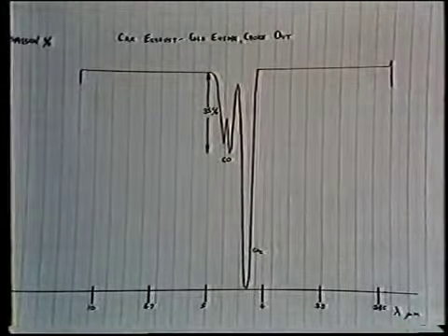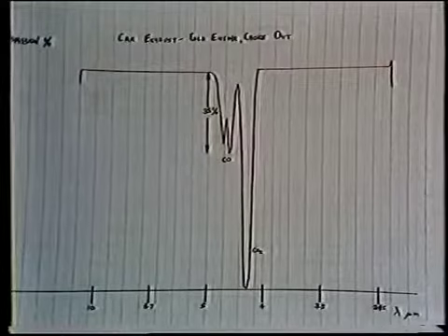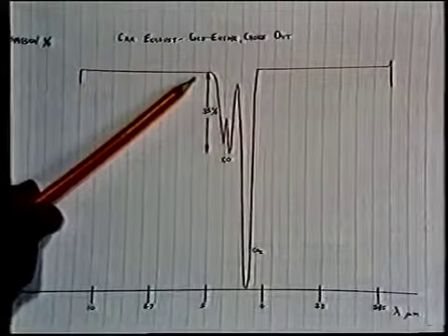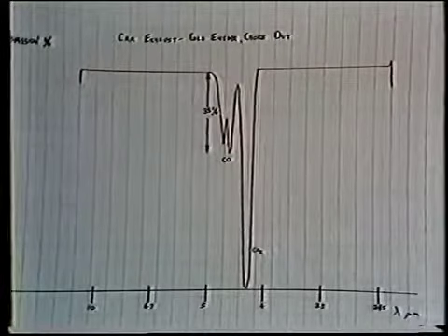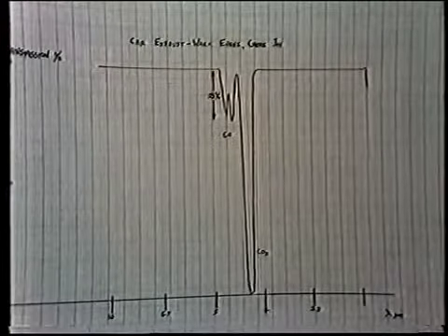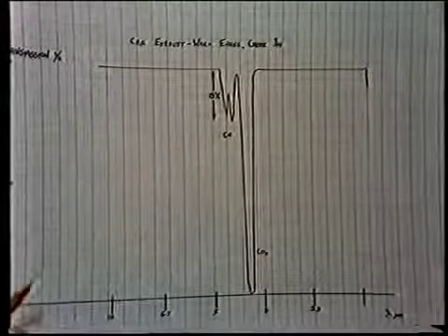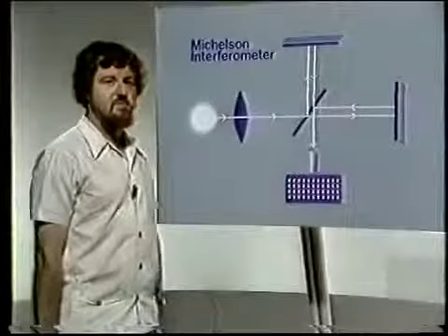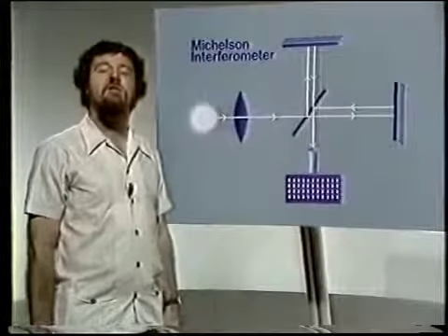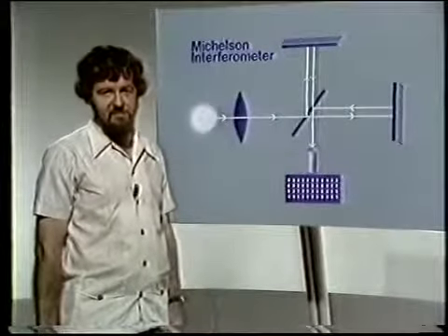Here's such a ratio in the case of a car whose engine was cold. There's a hefty absorption of carbon monoxide, so there's quite a lot of carbon monoxide obviously present. But when the car is warm, after the engine's been running for some time and the choke's been put in, we see that the absorption has gone down. The amount of carbon monoxide present has decreased. So you can see that by automating the output, we can examine the exhaust spectra and see a way ahead to solving the problem, to reducing the amount of pollution caused by car exhausts. We can solve a practical problem.